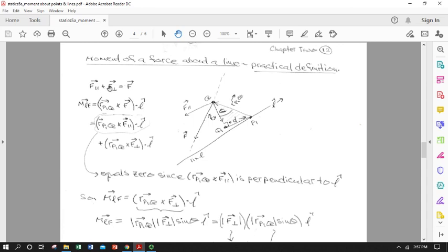And some of this might be because the part perpendicular is going to give a torque about that shaft, which might be good if I want it to rotate. The part parallel to it might make the shaft move and slip in a bearing axially. That's really bad. So I might just be concerned with the part that can turn it and the part that can slide it along its axis. So I can take a look at just resolving any vector I have into what turns and what slides. So it might be useful for anyone designing a mechanical system.